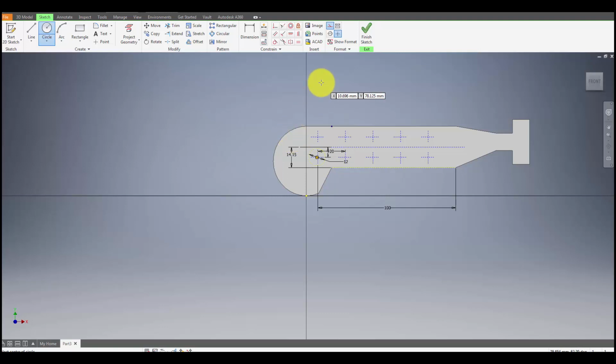Now we can change that to a solid line, so just escape from that, click on the circle, make it solid. The other circle is 10.2. Press enter. I've done the same mistake again.